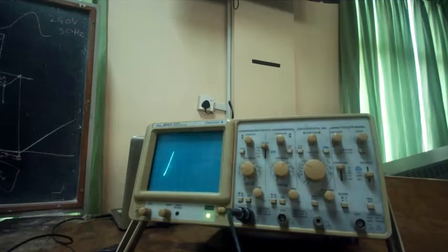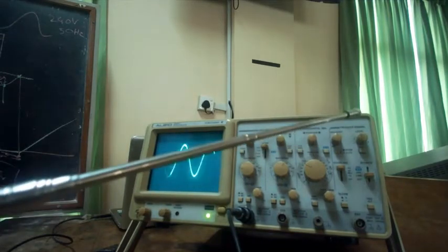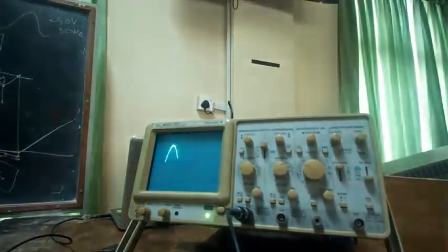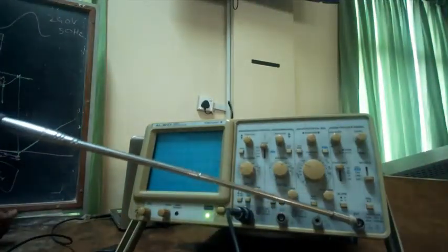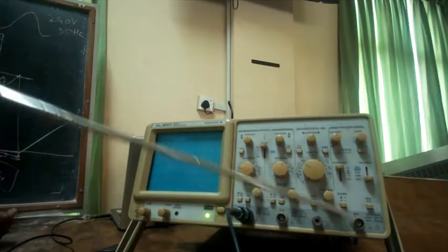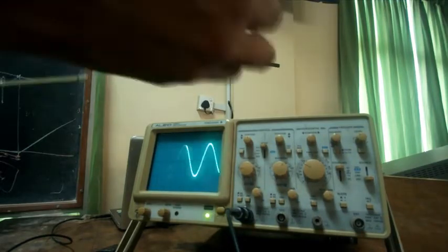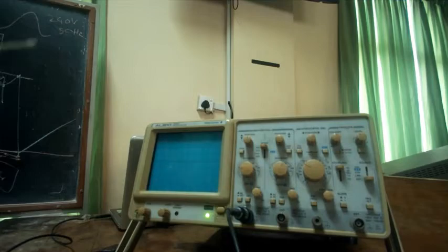So we know the operation of the trigger, and then there's also another one called external. There's this third BNC connector. That's the external signal. If you want to connect a separate signal, not the channel 1 signal, not the channel 2 signal, not the line 50 Hz signal, but a separate clean signal with the same frequency as the signal that I have, then I can use that to trigger it. A completely third one, external. So you understand that also.